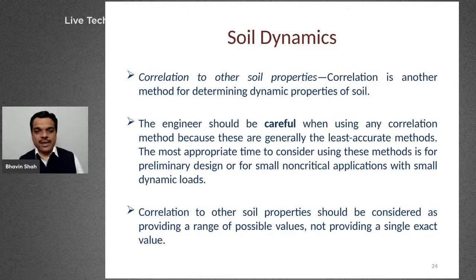But for all final design, drawings or calculations, we must use the refined value whatever we get from the geotechnical investigation report. And if we are considering the correlation to other soil properties, that also should be considered as providing a range of possible values and not a single exact value.